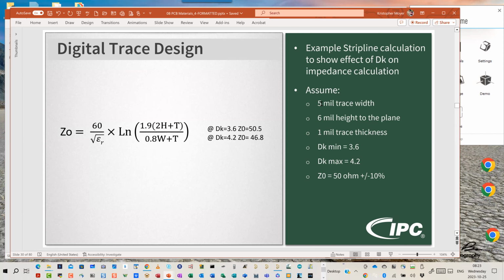Now, plus or minus 20%, right, on a 100 mil wide trace, for example, seems like a large number, but the reality is that the actual chemical etching processes used to fabricate the traces don't scale linearly like that. It's typically about plus or minus 1 mil, right? So let's assume that my etching capability can modify my trace width plus or minus 1 mil. Well, on a 100 mil wide trace, plus or minus 1 mil, that's 1%. I'm still nearly at target width.